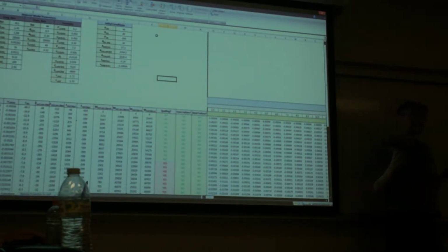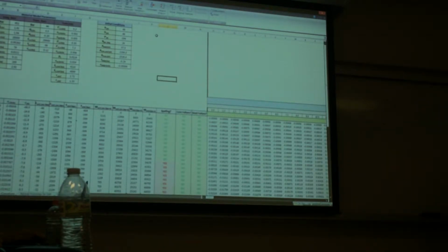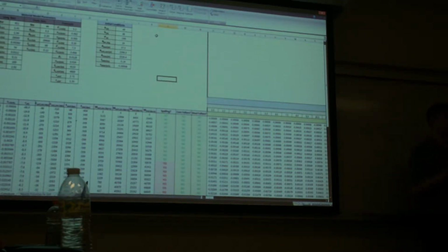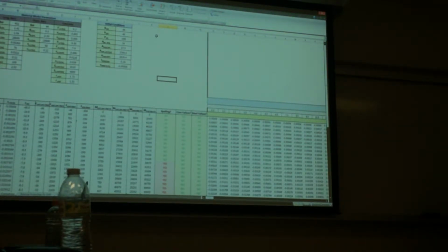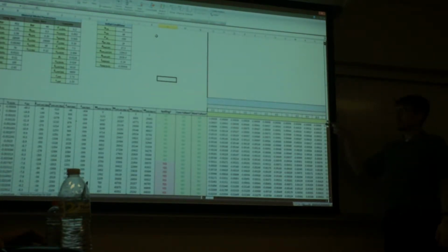So you have multiple materials. In order to get that initial strain state, you need to look at your steel and you need to look at your concrete and say these guys have different moduli of elasticity. Therefore, I want to convert these to be equivalent. So if I take the force divided by the area, I'm using kind of the equivalent area based on the modulus of elasticity of both materials. And once you have that equivalent area, you get stress is force divided by area. Then you can get your strain from that. Once you know stress, you now have your equivalent modulus of elasticity, so you can get strain. And then once you have that strain, you can get that strain in all your fibers.